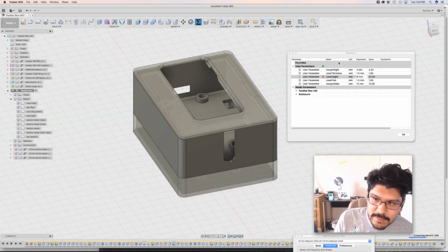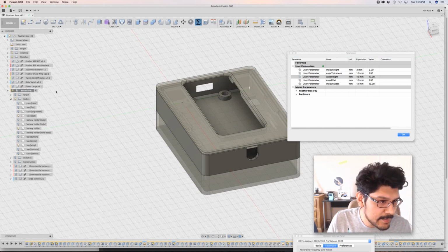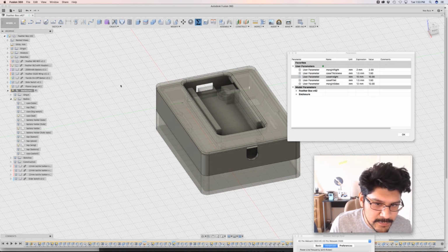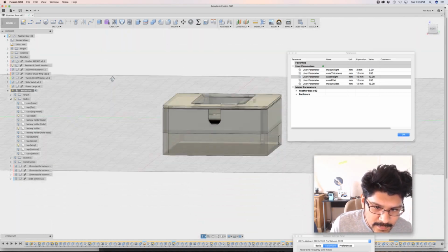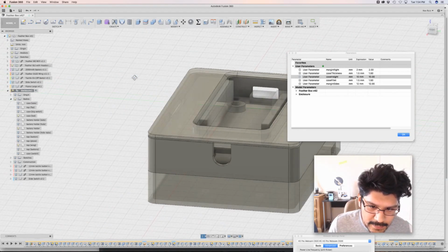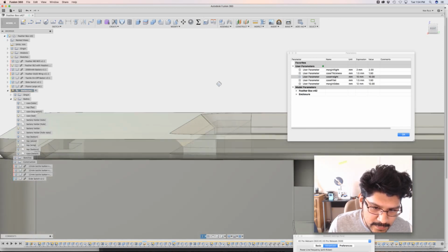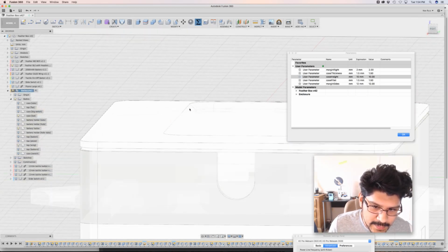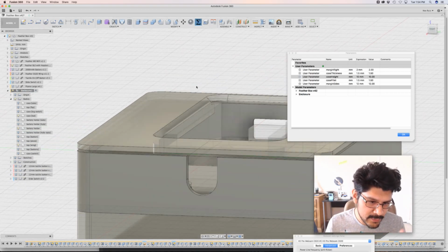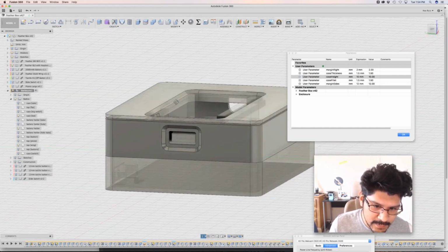One of the reasons why you might want to have a taller case is to completely cover up your feather, right? If we open up the regular feather, you'll see that it has some pretty tall looking female headers. These guys right here are the female headers, and they're just about intersecting with the topper. If I didn't have this opening for the wing, it would intersect, and you wouldn't be able to close the case all the way. So this is really the thinnest I could get it. 10 millimeters is pretty darn thin.